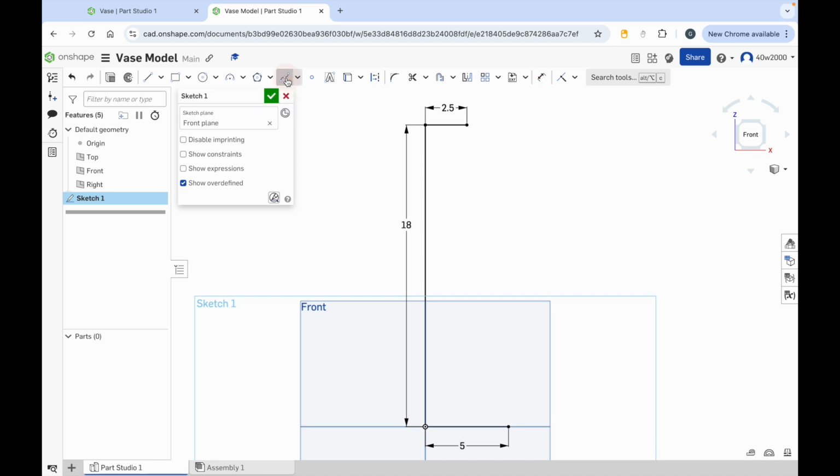So let's use that tool now. So make sure you've clicked it and it's highlighted in blue. And then go to the end point of your horizontal line at the top. Click that, move the mouse cursor down, and you can see it just looks like it's about to draw a straight line. But click to place a connecting point and then move the mouse cursor further down, and as you move it left and right you can see that the curvature of that line is affected and it gets either more curvy or less curvy.